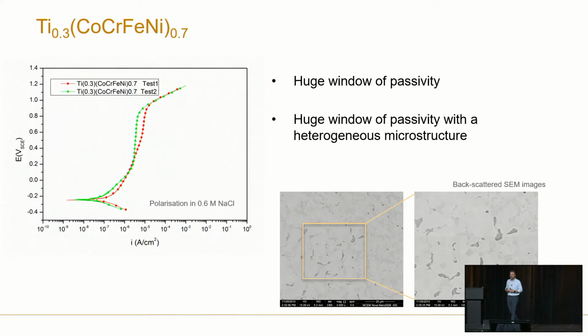And what we were really surprised with was that we just picked one of the many alloys that we tested. So this is a high entropy alloy. I won't bother talking about the notations, but what this means is it has less titanium than it has each of these elements, so it's not equiatomic proportions. And the reason why you'd sometimes deviate from equiatomic proportions is when you're calculating a composition before you make it, you want to make sure you have a high entropy of mixing, right? Because that's part of the process.